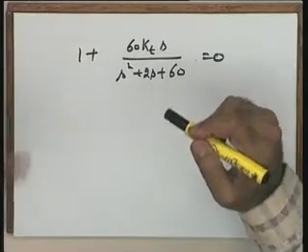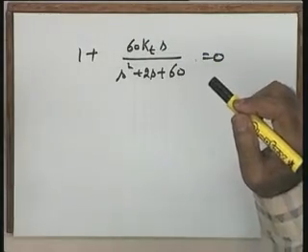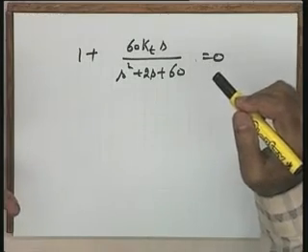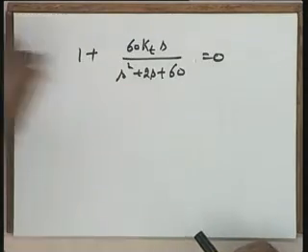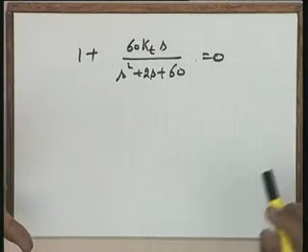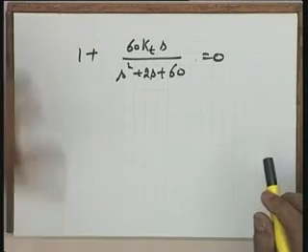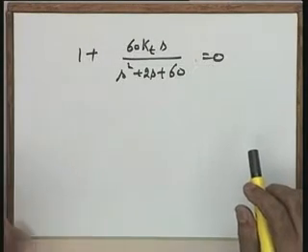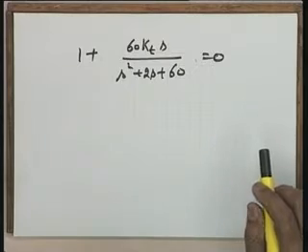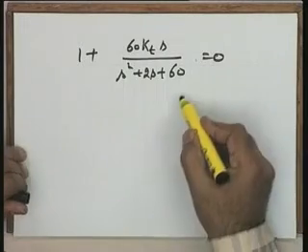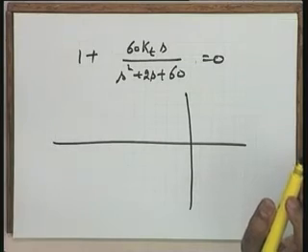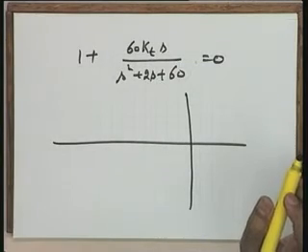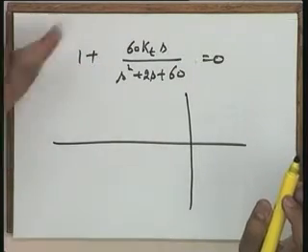The amplifier, I am taking one parameter at a time. So the amplifier gain Ka is fixed. In that particular case, I get this as the suitable characteristic equation for making the root locus sketch. I want you to give me the value of Kt so the damping of the overall system is 0.5. So I need the root locus sketch for this. Now poles and zeros are not necessarily the poles and zeros of the original system, they are the poles and zeros of the root locus function.